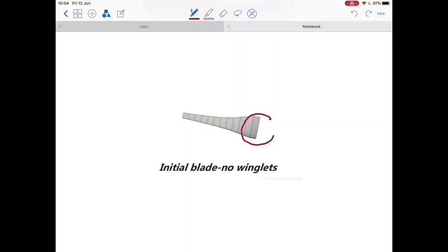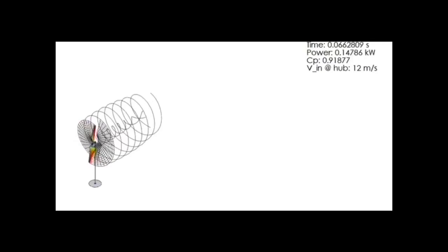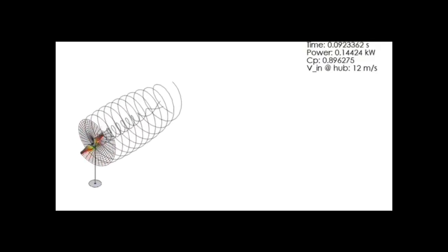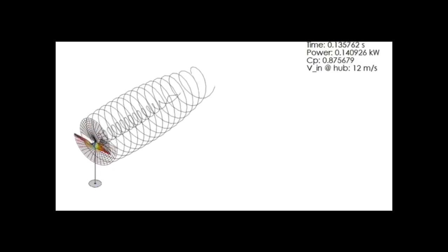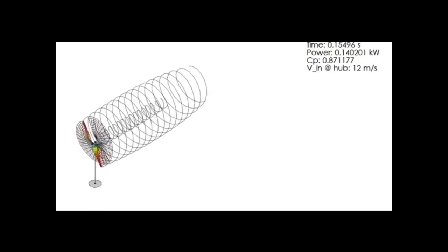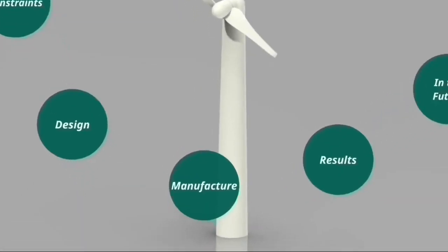It's worth mentioning that, to reduce possible extra drag, and for a better fit within the nose cone, we decided to decrease the chord length at the root of the blade. This, as well as the addition of winglets, may have slightly changed the optimal TSR, but this could not be fully simulated in Q-Blade. Finally, we also used Q-Blade simulations to check that the turbine was spinning clockwise.